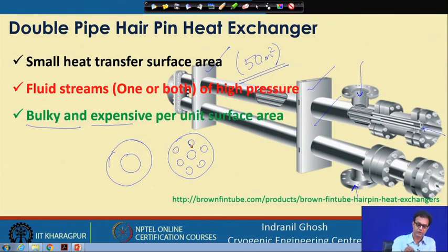So, it is not then a double pipe, it will have multiple tubes, multiple pipes. And it may also have, depending on the heat transfer coefficient of this annular space, if we find that the heat transfer coefficient of this annular space is small, then we may have to use extended heat transfer surface or fins on this side, on the outside of the inner tube.